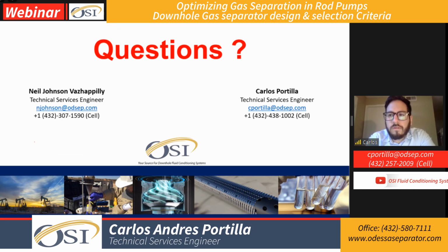So basically, yes, we can. What we can do is calculate how much gas is ingested by the pump, and then run a nodal analysis, like pressure and separation efficiency. So let's imagine we're ingesting, I don't know, 60 MCF of free gas, and then we will have a separation efficiency.